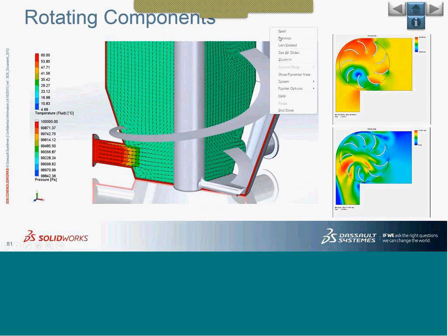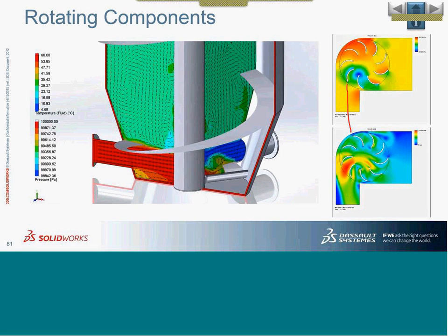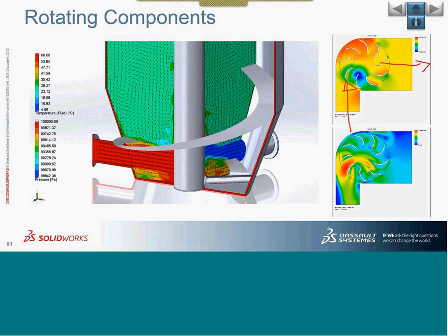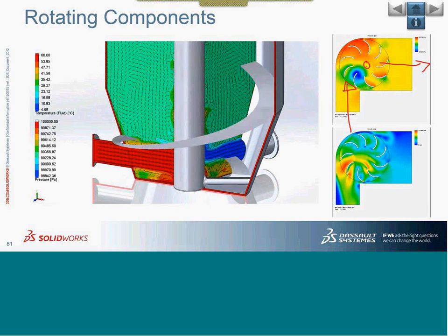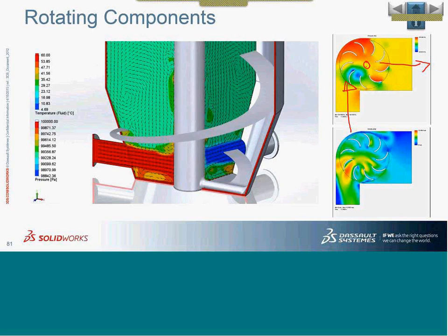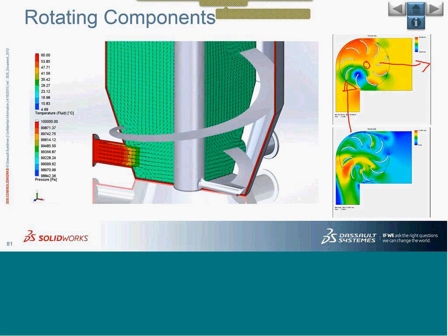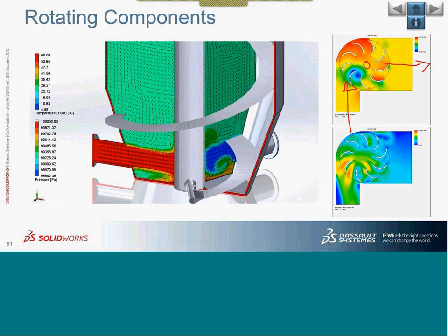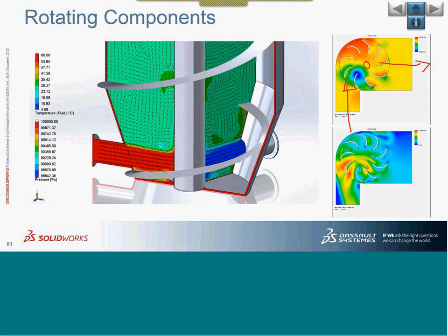So if I try to show you with a pen here, the requirement was the fluid should come like this, and either it should go like this, or outside as well. So that was a big limitation in the past, where we could simulate only certain kinds of pumps or turbines. But we have one more step wherein we can use a sliding mesh, and the limitation no longer exists, and we can actually simulate things like those shown on the screen.